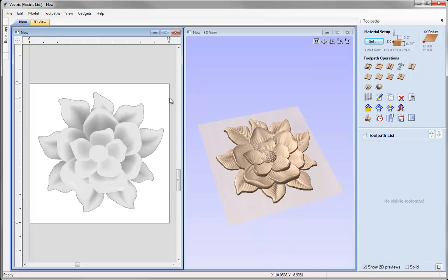On the Modeling tab, we have the component tree where we build up a 3D object potentially made of multiple 3D entities. The result of that component tree is what we see here in the 3D view and is referred to as the composite model. In this case, we only have a single object, so that's what we can see. But that is the object we're going to cut. What we have selected is totally irrelevant. It is always just going to cut the entire part that it finds within the 3D view.